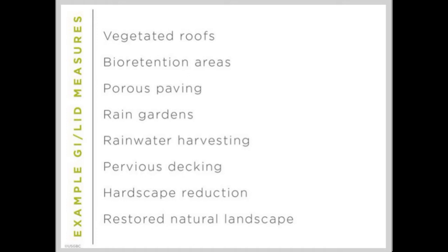In addition to mimicking natural hydrologic cycle processes, green infrastructure and low-impact development help to integrate the site with the surrounding watershed, are appropriate to local ecosystems and climates, and deliver such other benefits as water reuse, habitat creation, and species diversity. Examples include better site design principles such as minimizing land disturbance, preserving vegetation, and minimizing impervious cover, and design practices such as rain gardens, vegetated swales and buffers, permeable pavement, rainwater harvesting, and soil amendments. These are engineered practices that may require specialized design assistance.